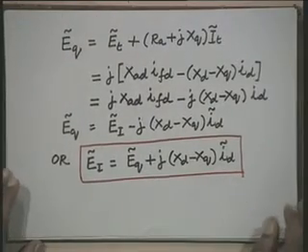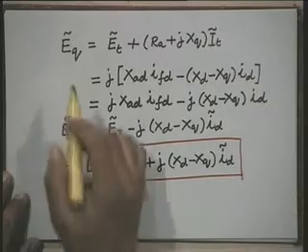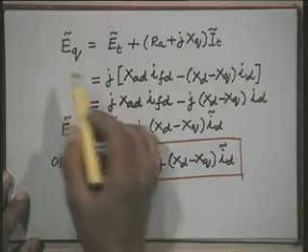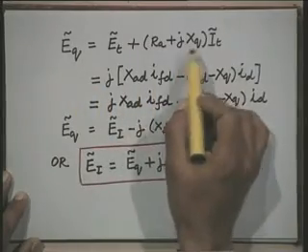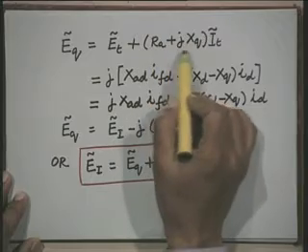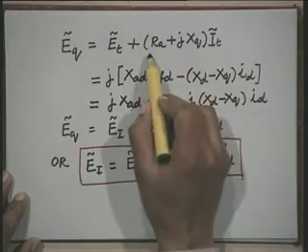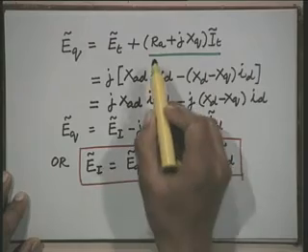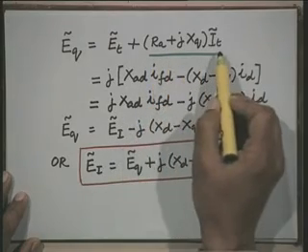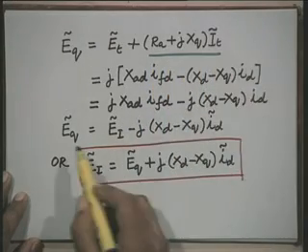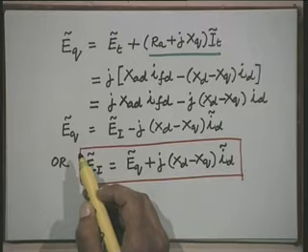Then earlier we had defined one term E Q, that is the voltage behind the impedance R a plus j times x q, that is terminal voltage. To this terminal voltage we added this term, that is R a plus j times x q into I T. This term also came out to be along the q axis.